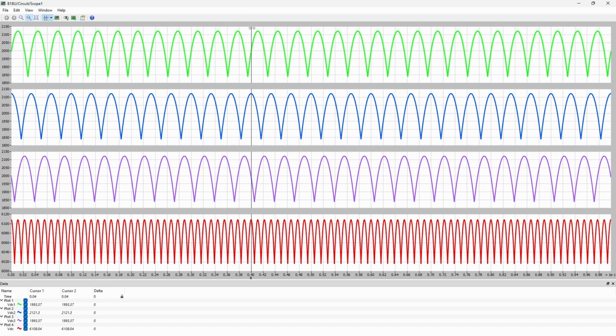That means if we take 20 milliseconds, we can write 0.02 here and position it somewhere reasonable, like here. If we count each partial DC voltage, it should be 6 pulses because they are all B6 bridges. So if we count 1, 2, 3, 4, 5, 6, and also the same for the other two.